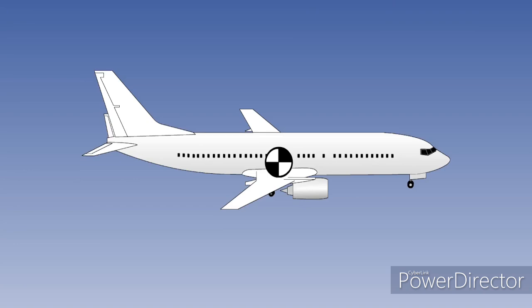Within the loading of the aircraft, the centre of gravity is more significant than the mass itself, as it affects the aircraft's resistance to spinning, as well as its behaviour in the spin. A CG near the forward limit makes the aircraft more stable, with higher control forces, which make it less likely for the pilot to make large, abrupt control movements. The aircraft will be easier to trim, but its stalling speed will be higher than with a neutral or aft CG.